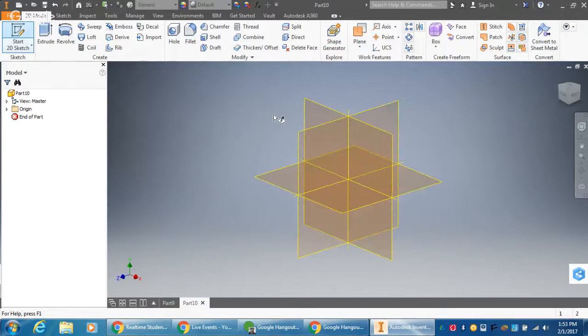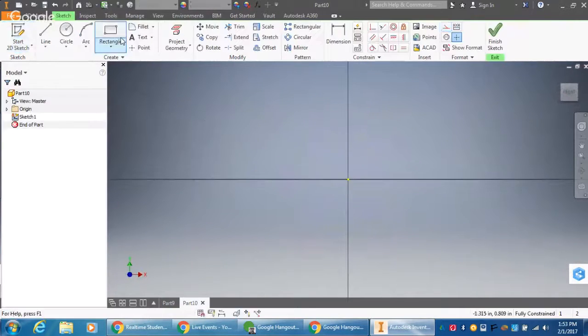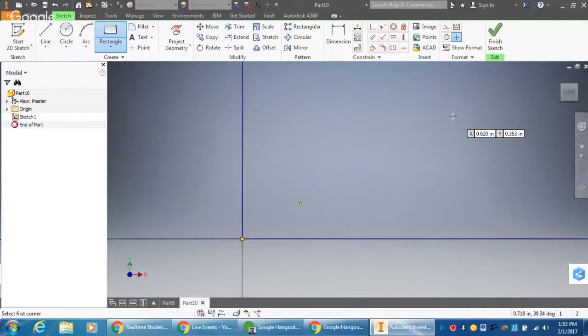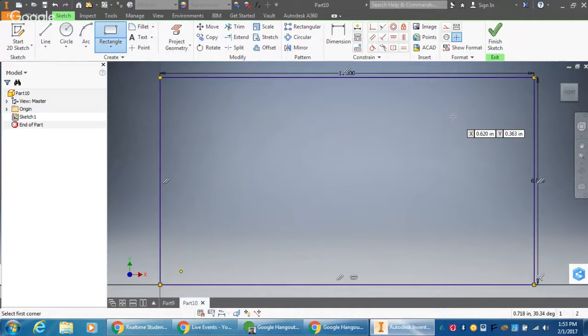Anyway, I'm going to start a new 2D sketch on the XY plane, and draw in a 2-point rectangle just like I did before, though we're going to do something a little different with this. This one happens to be 11, tab, 6, enter, home key, and then we're going to start off with this base. I'll hit escape to unselect the tools, and let's talk about the kind of shape that we want here. I know that I need a little 1x1 rectangle in the center here.